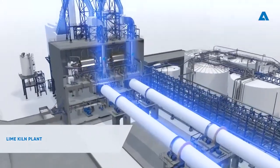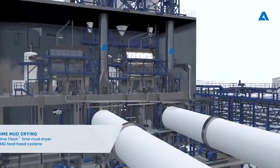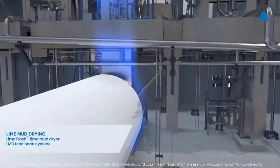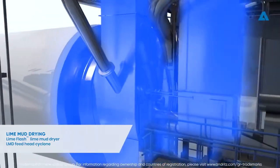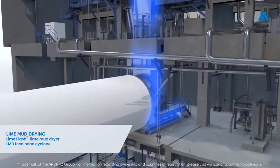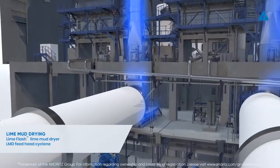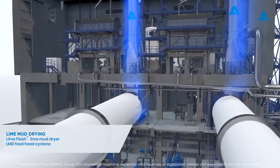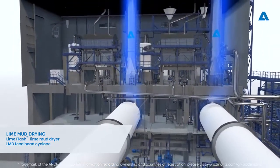The processes in the lime kiln plant happen as follows. It starts with lime mud drying. Washed and mechanically dewatered lime mud is fed from the lime mud filter by a conveyor into the screw feeder and further into the lime mud dryer of the lime kiln. The lime mud dryer is a vertical duct starting directly from the lime kiln feed end and is tangentially connected to the cyclone.